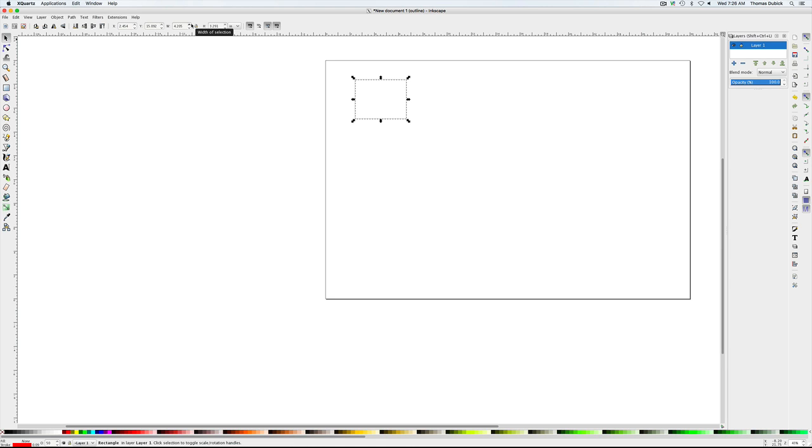All right. So the way we go about this, let's go ahead and set the size of our slot. We're going to make it a 1/2 inch wide. And this slot can differ depending on your needs. And I'm going to make it 0.15 thick, 0.1500 thick. So there we are. That's the thickness of cardboard.